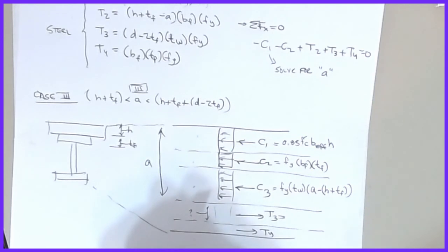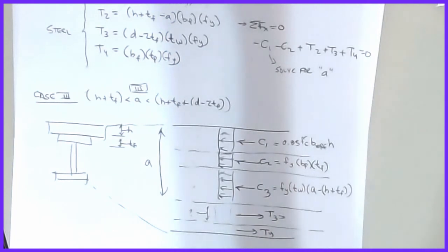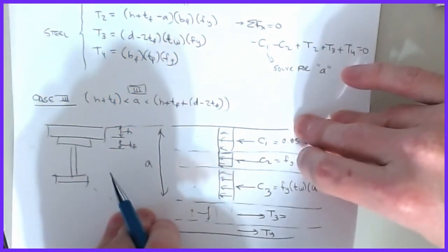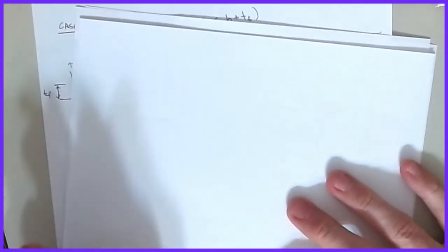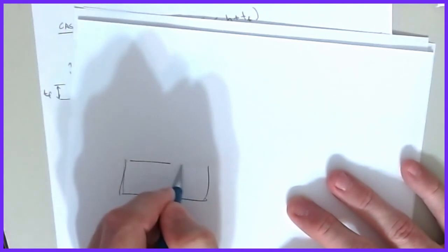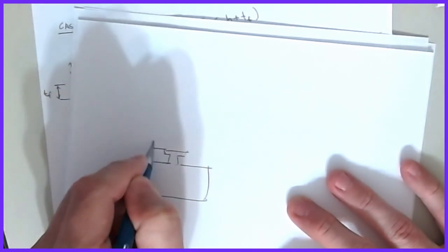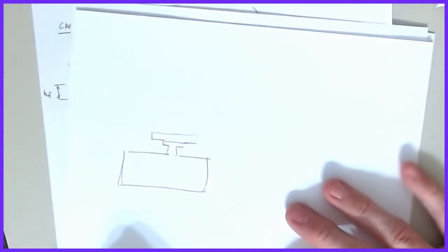For I-beams, W shapes, and S shapes, generally it's either case 1, case 2, or case 3. If you had some really bizarre, disproportionate, custom-made steel shape that looked like this, and a little bitty guy, and then a slab that looked like that, I could pull that thing all the way down into the bottom, but it doesn't happen on most standard shapes very often. But the construction technique is exactly the same.